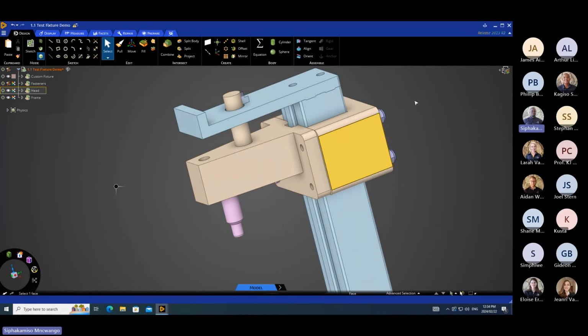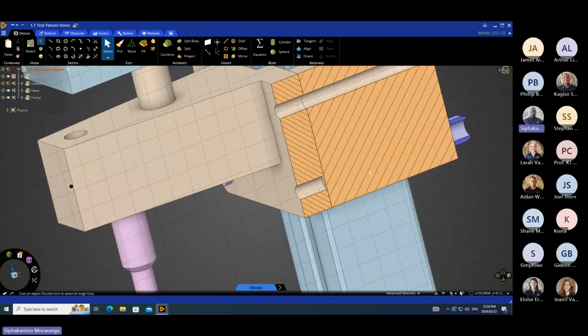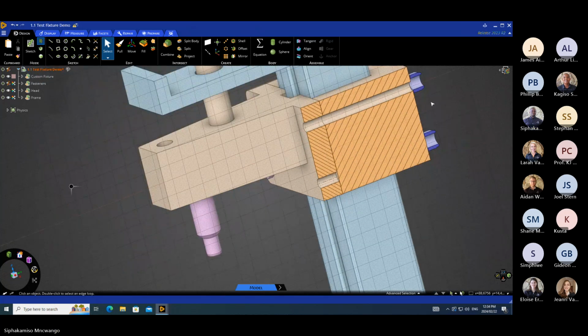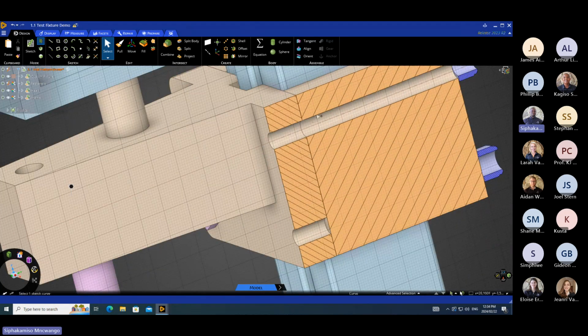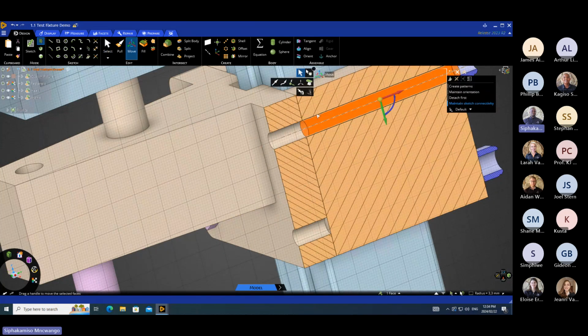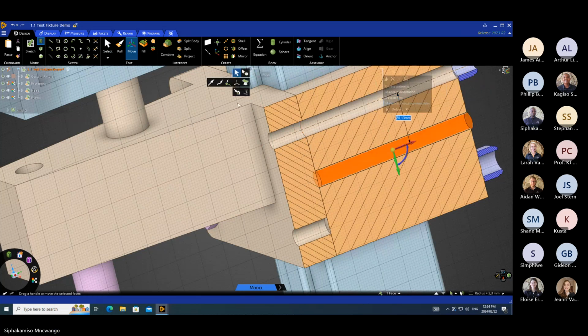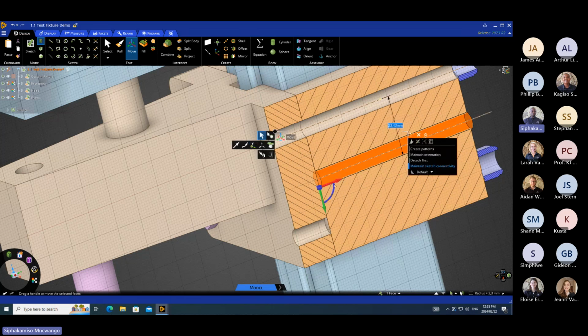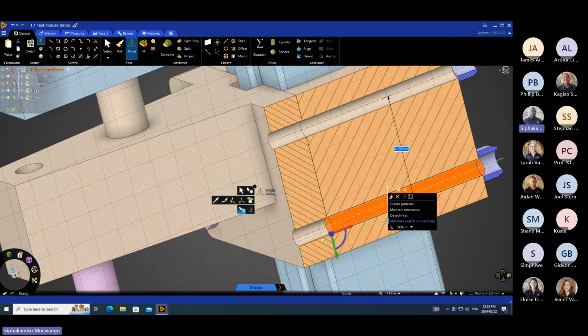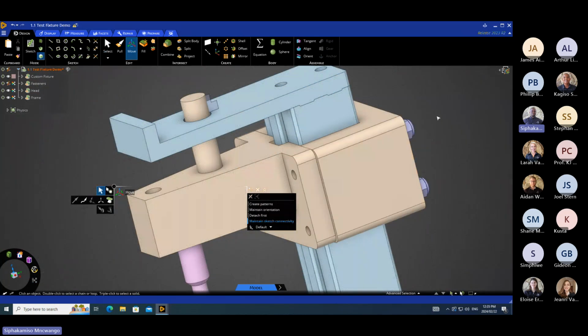And then if you want to quickly go back to your section mode, you can right click and then use last sketch plane. And we can see here that we don't have a hole. So what we can do is we can come back here, we can click this hole, we can move it, and then holding control and moving it at the same time will create a duplicate of that hole. And then we can quickly anchor it here, and then we can use the up to, pressing U or using it here in the X, and then pull it up to there. And then we can press D to go back to our full mode again, and then show all.